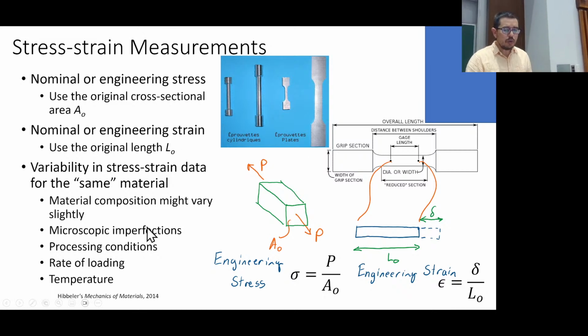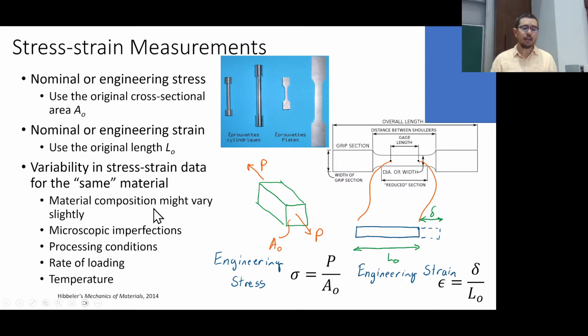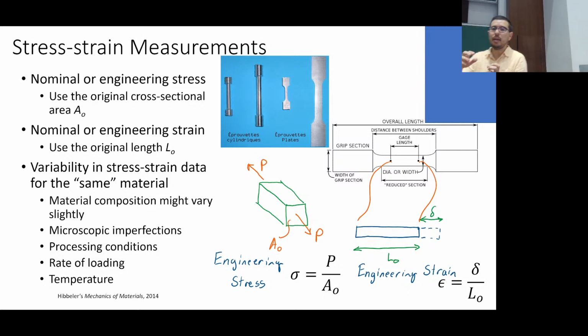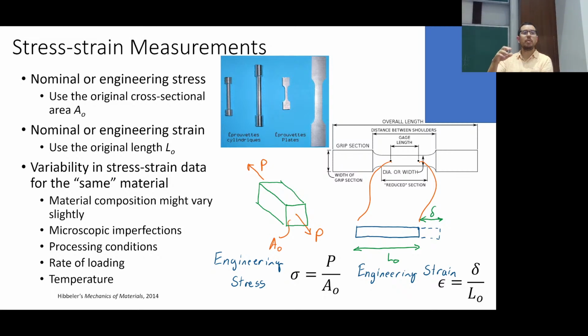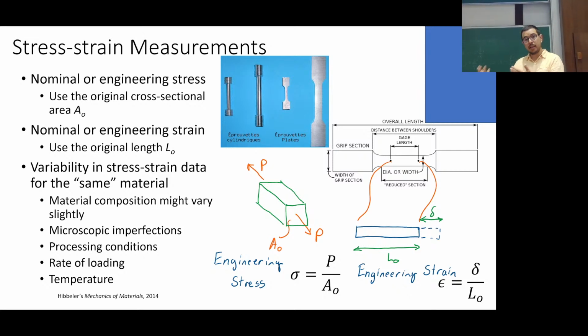So there is quite a bit of variation in these types of tests. We're not going to do major statistics here, or pretty much any statistics, to be honest. But you can appreciate that one sample is not going to break at the same force, same stress, or same strain as another sample of that same material. And so what we do, and we'll talk about this later in the class, is prescribe safety factors.